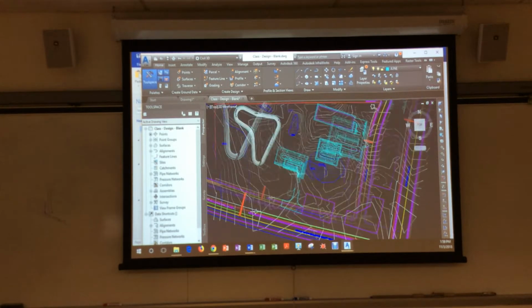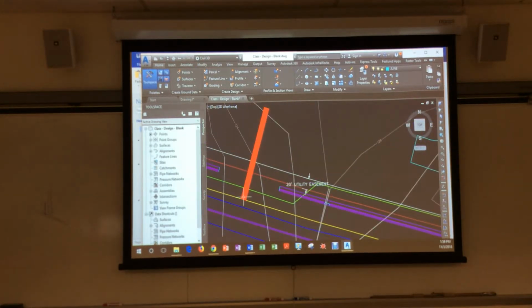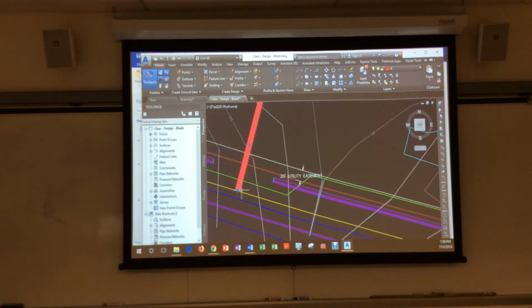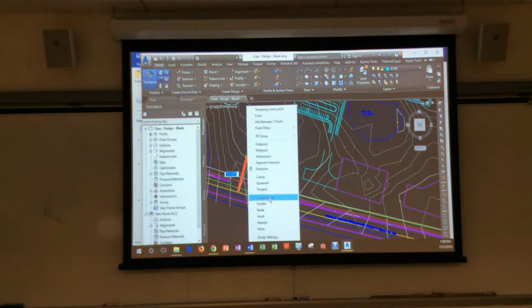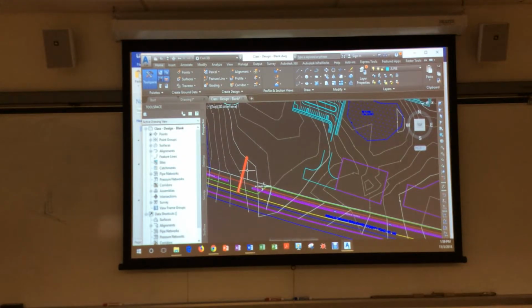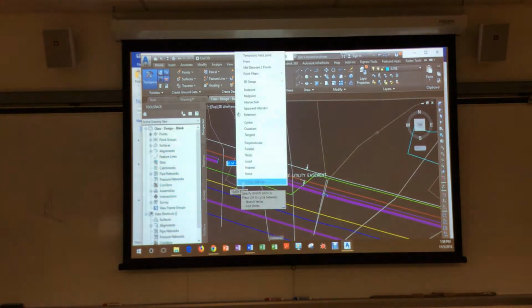So what I'm giving you is this set of plans. What I mean by the tie-in point, this down here, this grip is your tie-in point. You don't have to follow the line right here. You can, as long as it's perpendicular, when you bring it in, shift perpendicular. Make sure that it's perpendicular to this yellow line. Okay?